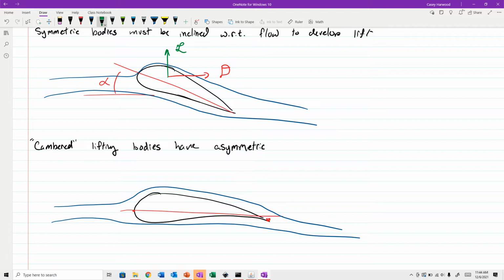So if you want an airplane wing where generally you want the lift to be in the direction that is not driving you into the ground, they're going to be optimized so that they develop a positive lift at an appropriate range of angle of attack. Whereas if you look at the tail of that same airplane where it has a rudder, where you want it to be just as good at turning left as it is at turning right, then you want to use a symmetric body so that its performance is the same in either direction.